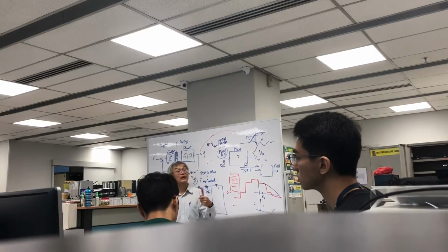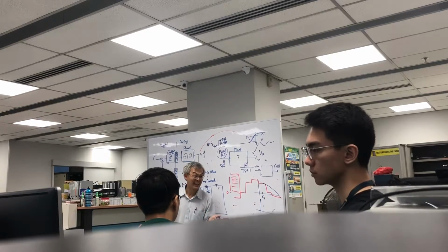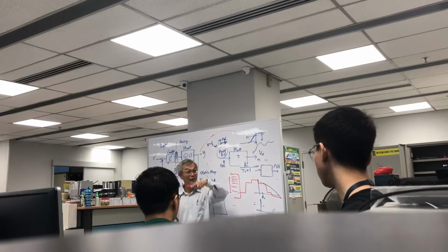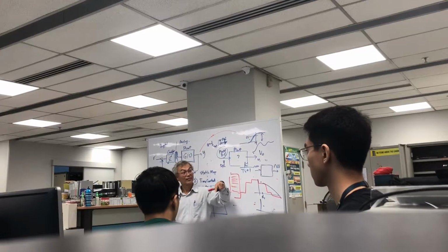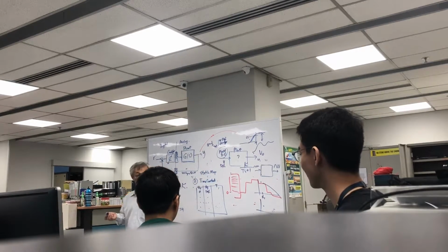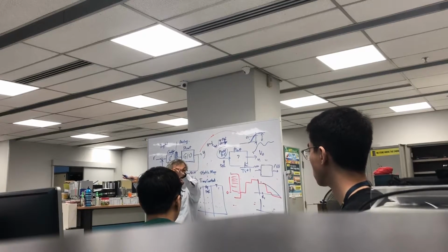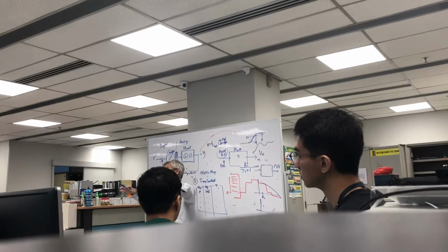So in principle you can do a crude frequency response, but it will be too hard because then you have to generate a sine wave. Generating a step test is easier. So in your case, how do you generate a step test? You just set PWM to 30%, let it stay for a while, everything settles down very fast.